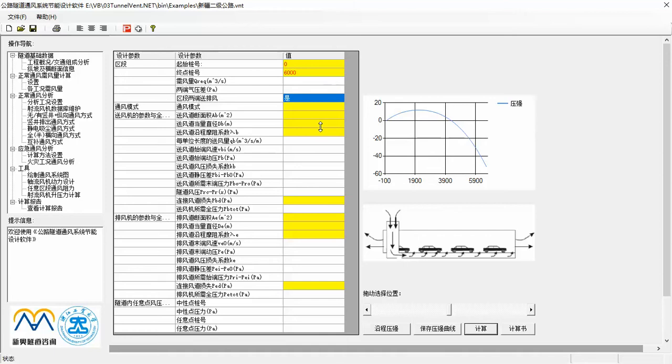Generally speaking, for unidirectional tunnel, semi-transverse mode with billowing airflow is recommended, so the piston effect can be made the best use of. While for bidirectional tunnels, totally transverse mode is favorable.